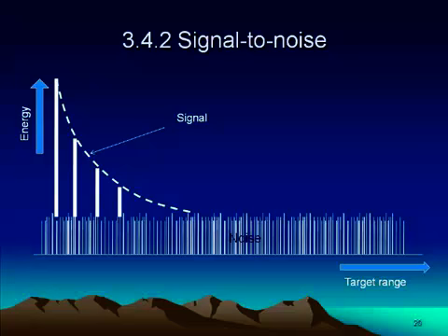But if the target is relatively very far, the received signal is going to be much less and just crosses the noise floor, and the receiver will be able to respond somewhat properly sometimes, not so good at other times. But if the target is much beyond this, definitely the received signal will be submerged in the noise and hence will not be detected. This gives us a clue regarding the unambiguous range determination of a radar system.